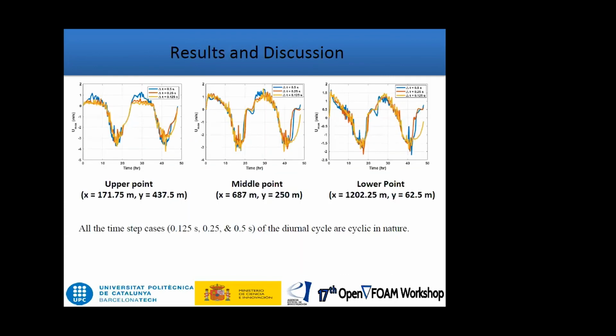Coming to the results, I have simulated three cases. The simulation setup has been run with time steps of 0.125 seconds, 0.25 seconds, and 0.5 seconds. The mesh size is 0.09 meter, the location of the first grid point above the wall.